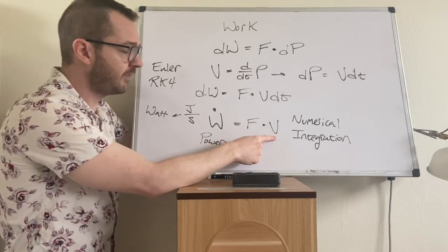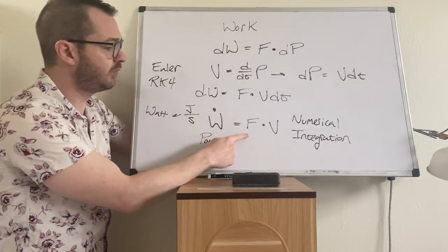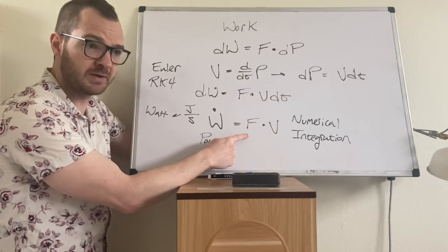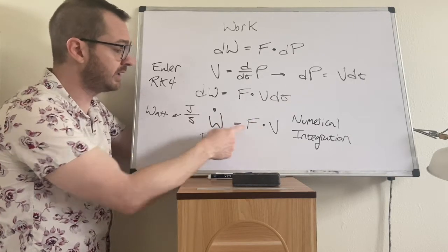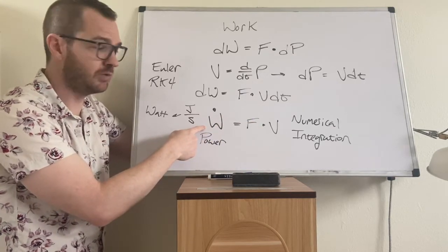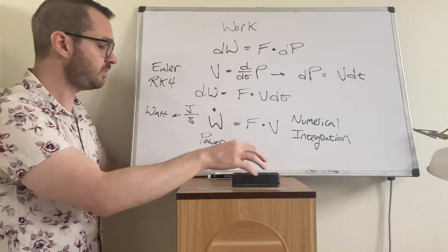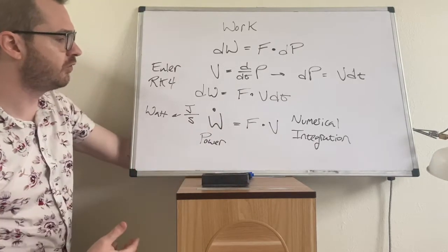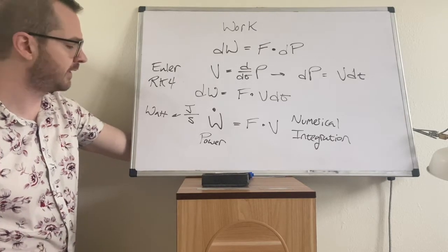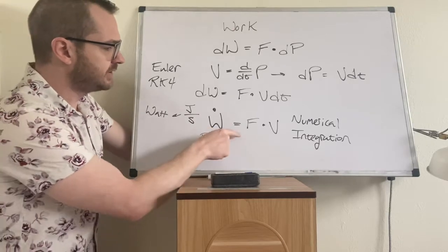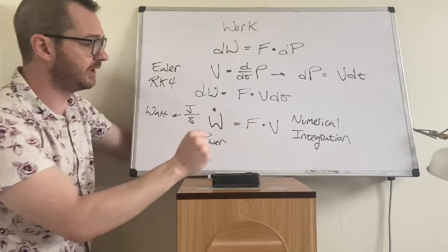You're going to always have an instantaneous velocity vector accessible, and you will always be able to solve for the aerodynamic drag. So inside of your simulation file, you calculate this W dot value, and then you numerically integrate it along with the rest of your variables. And then that will give you a running total of the amount of energy that you have lost due to drag.